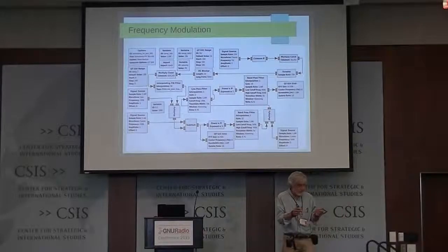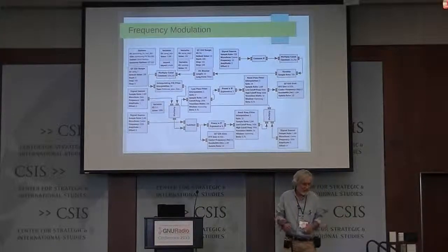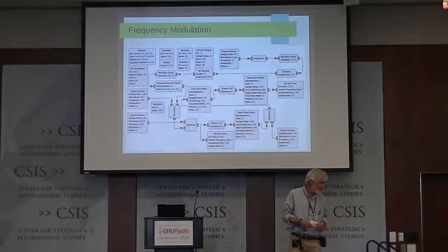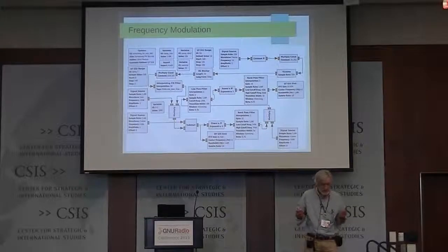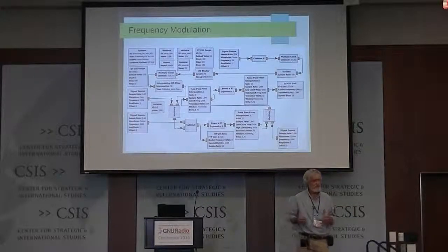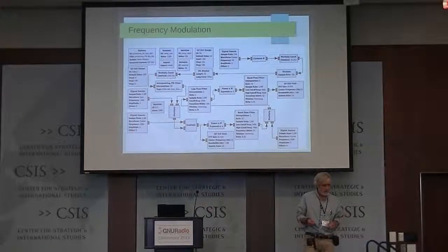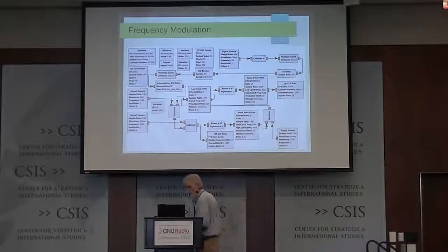They wanted, if you make a frequency deviation of, say, 10 hertz, to only use a bandwidth of 20 hertz on a signal that was 3000 hertz maximum. You can demonstrate that, and you can also demonstrate, if you actually have an FM signal, how to measure your frequency deviation or your modulation index, and so forth.